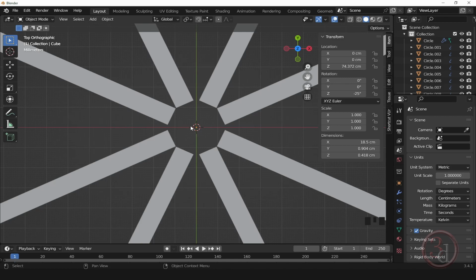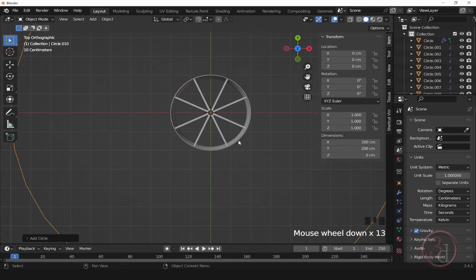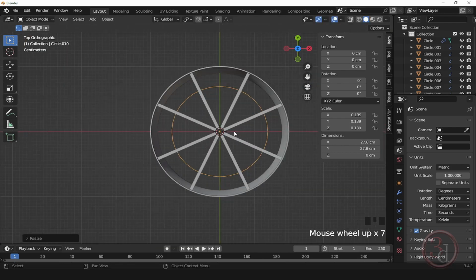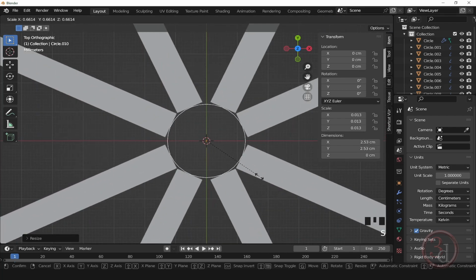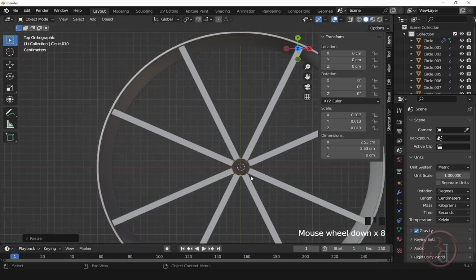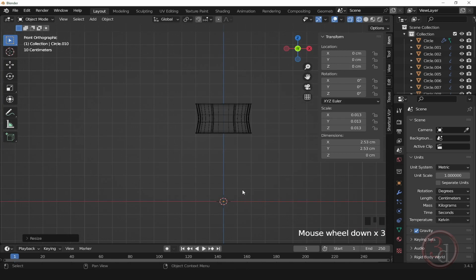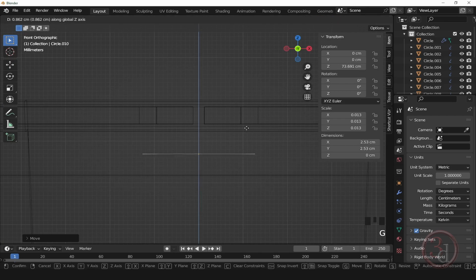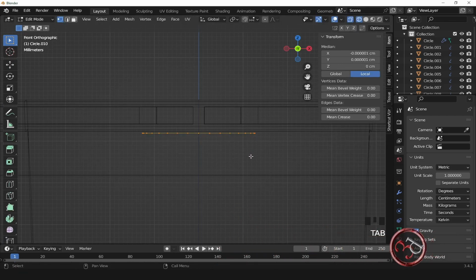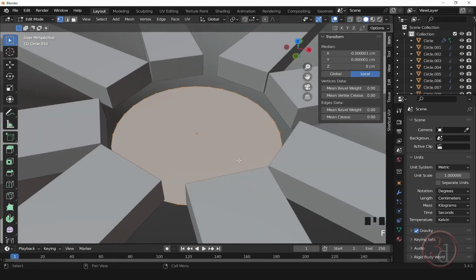So you guessed it, the shape will be a circle. So I'll create a circle mesh, scale it down, scale it down all the way here, and then just move it up in place. Press G to move. Just bring this up all the way here, and then go into the edit mode, and I'll press F to create the face, and